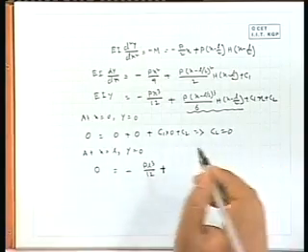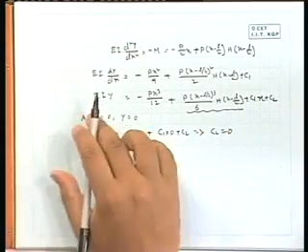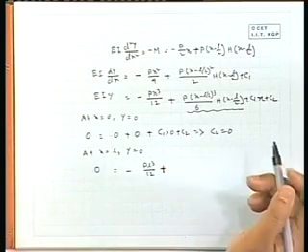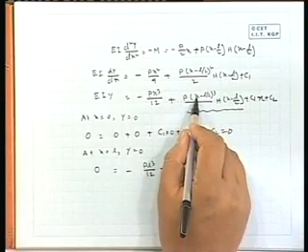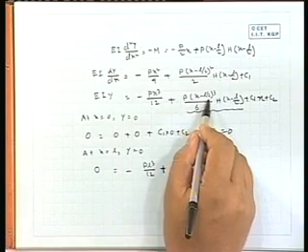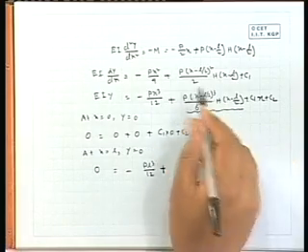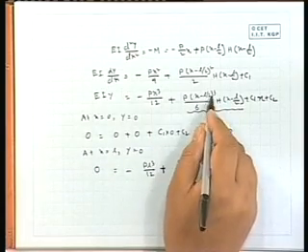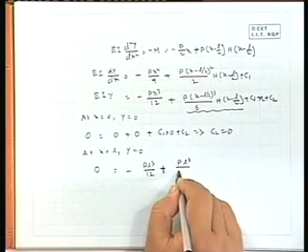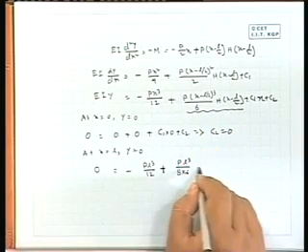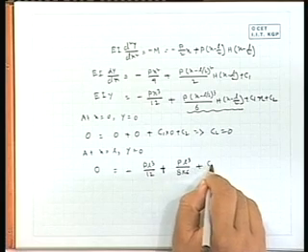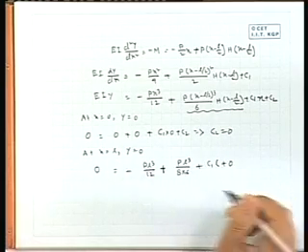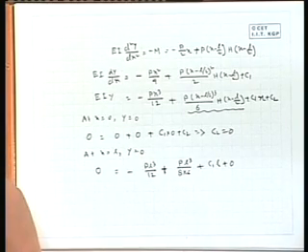You should remember that this part will not be there in the earlier case, but when x is greater than L by 2 it will be there. So, if I put x equal to L, it will be L by 2 to the power 3. So, it will be P L cube, and the denominator will be 8, and 6 is already there, so 48, plus C1 L, and C2 we obtained as 0.